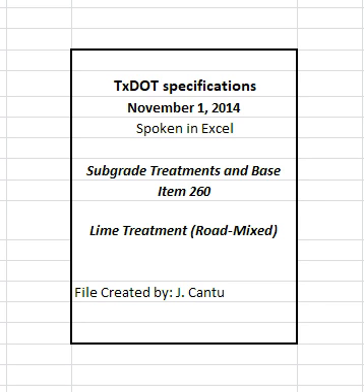When dry quicklime is applied as slurry, use 80% of the amount shown on the plans. Distribute slurry uniformly by making successive passes over a measured section of roadway until the specified lime content is reached. Uniformly spread the residue from quicklime slurry over the length of the roadway being processed, unless otherwise directed.